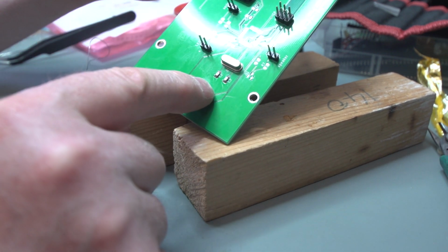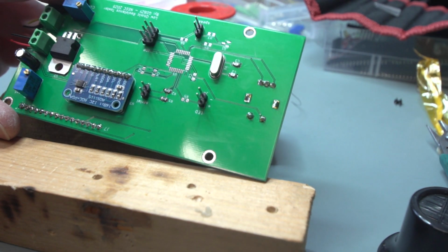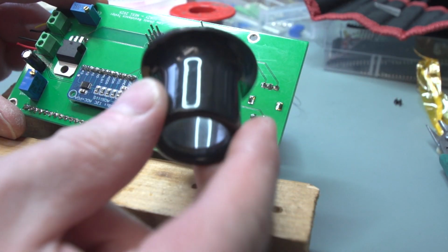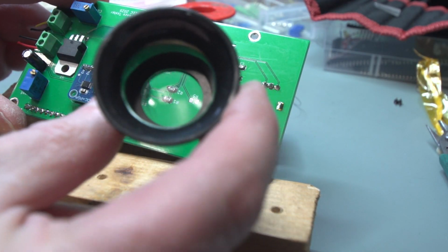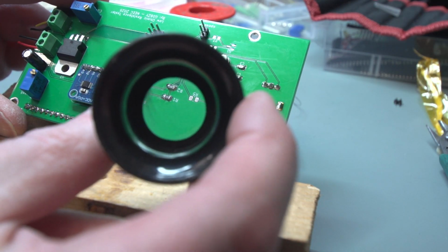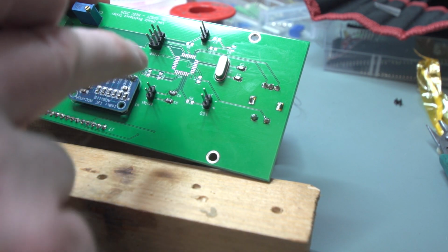Right, so we can now continue. Put some more resistors and stuff on. And I'll just get my loupe and make sure that actually looks okay. We'll have a look through there and make sure it all looks neat and tidy. Again, at the end, we'll finish off by cleaning up with some isopropyl alcohol and get rid of all the flux residue.